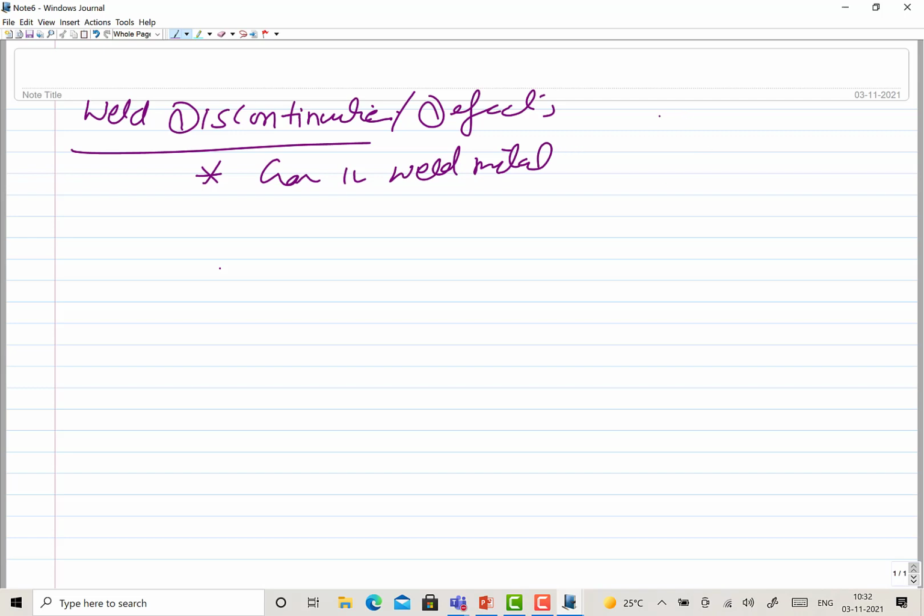When you have produced the molten metal, the atmospheric gases get dissolved and could not come out, so they are trapped inside the weld metal, leading to pores. The gases in the weld metal were unable to come out due to the rapid solidification, leading to the development of pores.